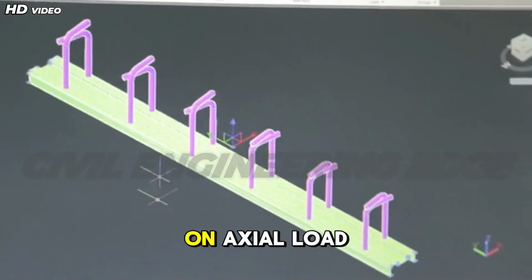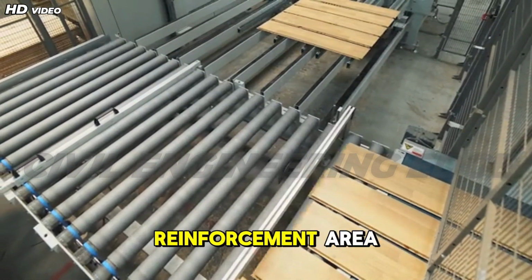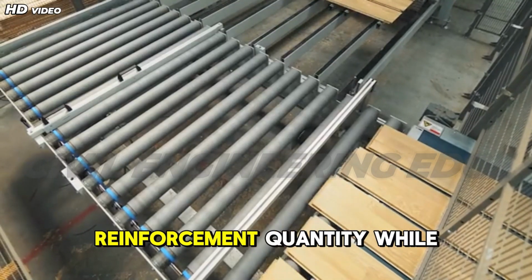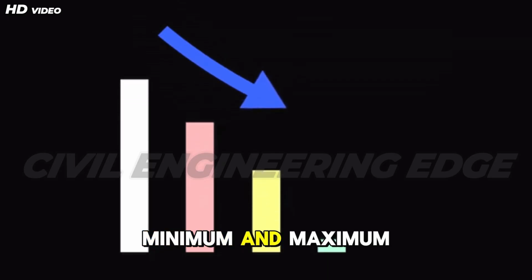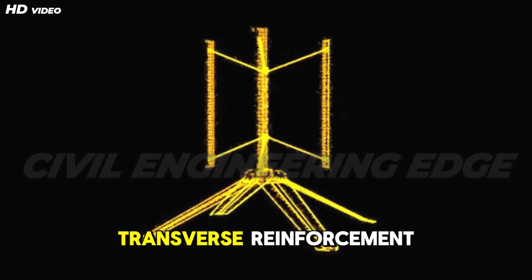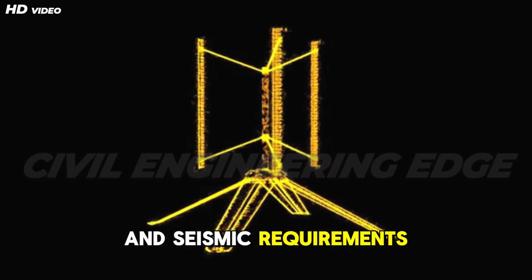Reinforcement selection depends on axial load, bending moment, and slenderness of the column. Higher loads and moments require greater reinforcement area. High-strength steel grades such as Fe500 are commonly used to reduce reinforcement quantity while maintaining strength. Codal limits on minimum and maximum reinforcement percentages must be followed to ensure ductility and prevent congestion. Transverse reinforcement spacing is selected based on column size, reinforcement diameter, and seismic requirements.